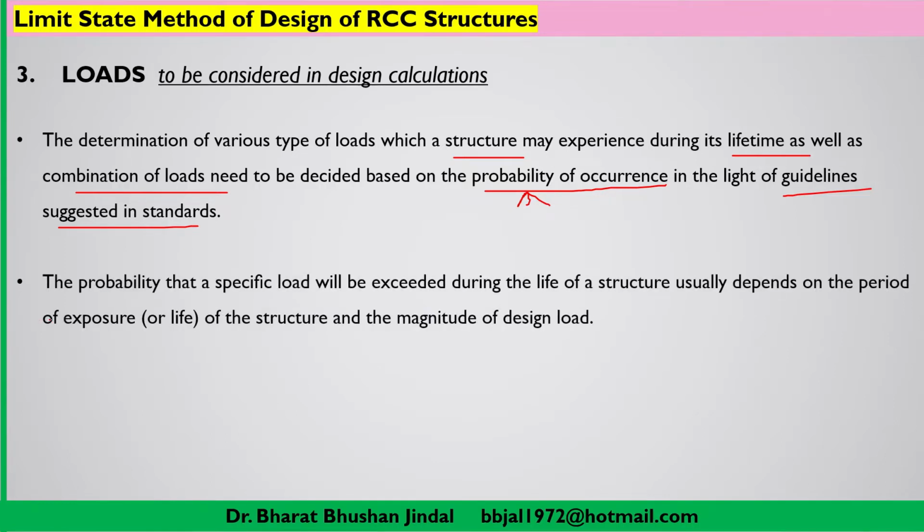The probability that a specific load will be exceeded during the life of a structure usually depends on the period of exposure, that means the life of the structure, whether that specific load, any type of load, can exceed its limits which we have taken into consideration while designing the structure. It depends on the exposure of the structure, how much lifetime you are expecting for a particular structure when you are going to design, as well as the magnitude of the design load.